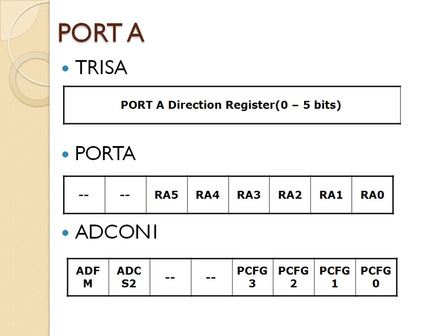Other than those two values, port A and port E will be working as analog inputs. So if you want to use port A or port E as GPIO, you have to configure ADCON1 to 0x07 or 0x06. Here 6 is nothing but 0, 1, 1, 0, and 7 is nothing but 0, 1, 1, 1. This configuration will make port A and port E act as GPIOs, not as analog inputs.